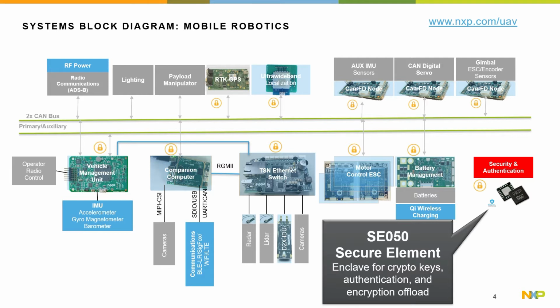So you may have a companion computer that has secure booting, but at a later date you want to allow late key injection. Say you want to authorize someone to use this or perform this particular flight, or you want to take a module that's securely booted up and associate it with a particular vehicle. So those are some of the things you can do with secure element.